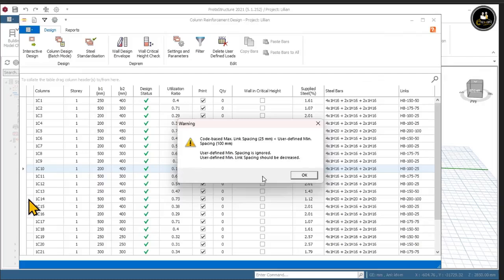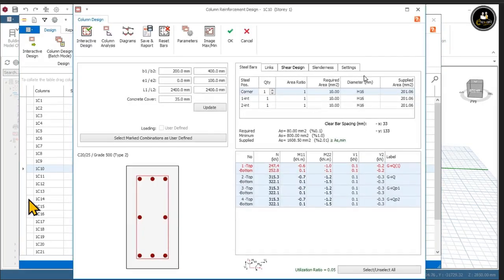Click on it. So you can actually remove the rebars, the reinforcements. This one, that is center. I think that's center 2. Just click there. No, return those. Remove the one on top. Yes, actually that's how it ought to be. Then just click OK.